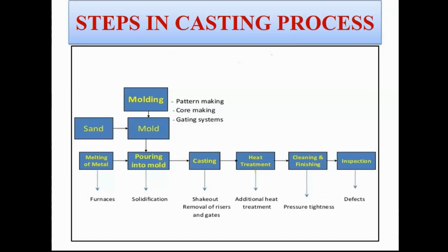And sometimes you can reduce the amount of residual stresses with the help of shot peening or grit blasting. So grit blasting involves the bombardment of small grits made up of sand particles, or it may be made up of small steel balls that are bombarded at predefined flow rates on a particular section of the casting. So it performs two functions.